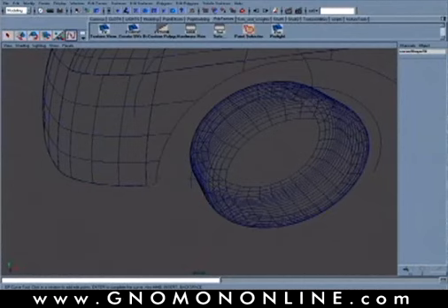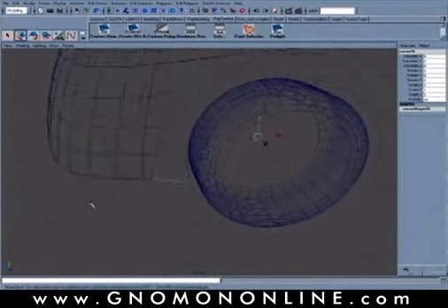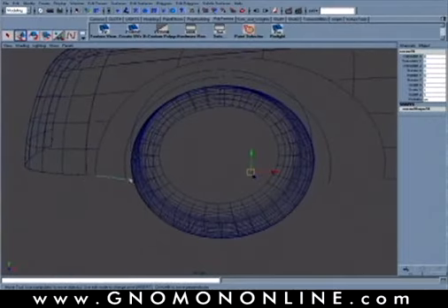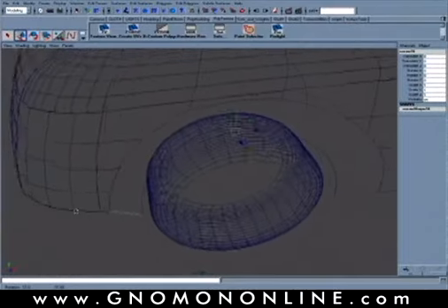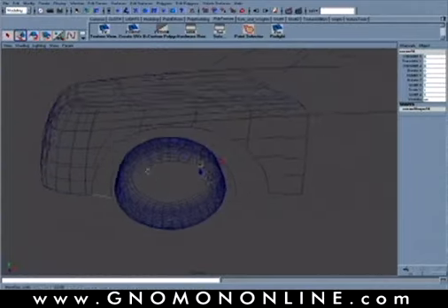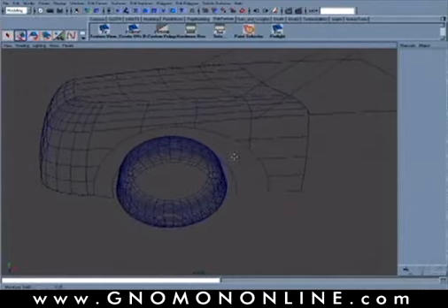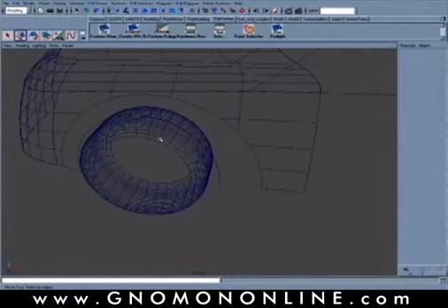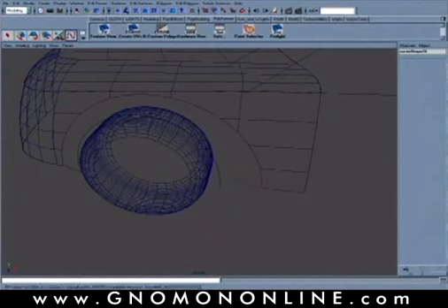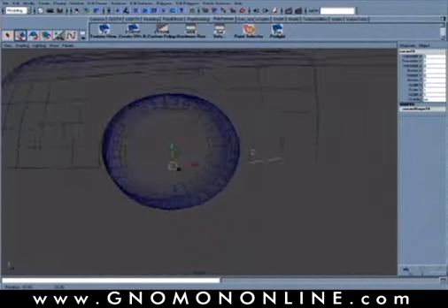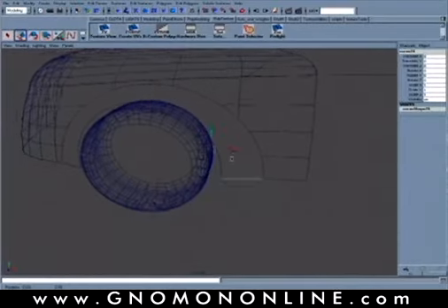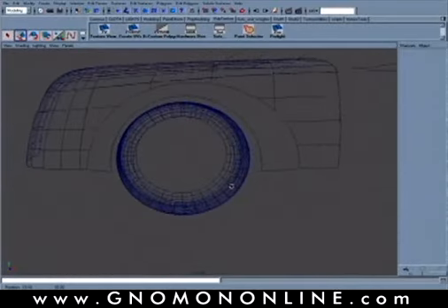Our next point will drag down to the extending curve coming off of that surface. And you'll get basically bridging the connection between that inside curve and the outside curve. The next thing we'll do, let's get rid of this back curve here, is create the other curve. So I'll go back to my edit point curve tool, curve snap from here onto that other opening. So we've created one complete closure at that point. Now, this is enough that we can build a square surface.